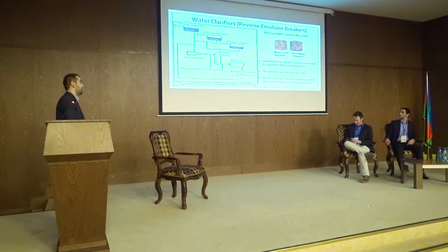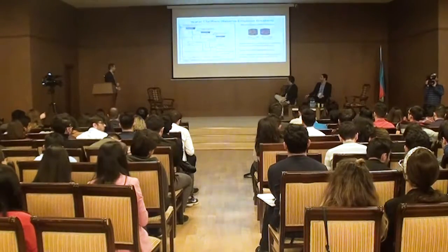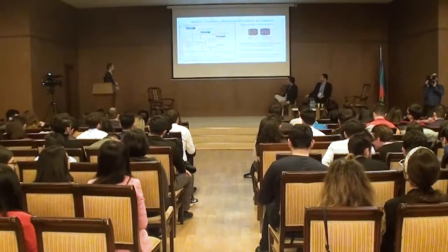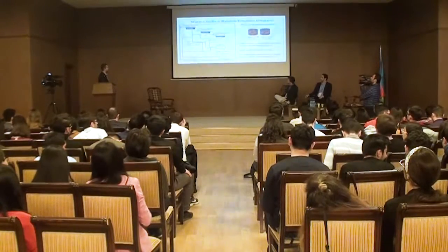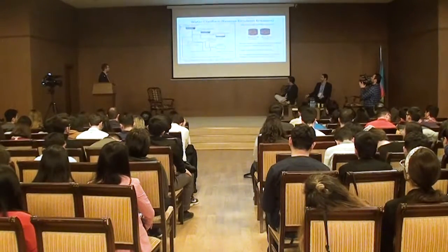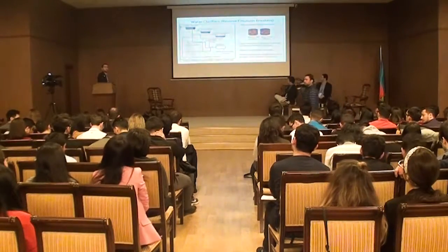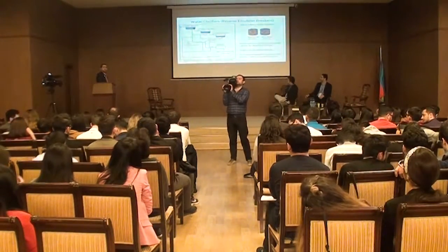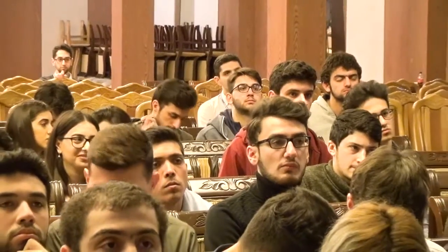So you don't want this because it may plug your pumps, filters, or injection equipment. And I put a typical offshore produced water system in North Sea. While we have water separation in this part of the system, this is a multi-stage separation system where we have water separated here and oil separated here, which is sent for further treatment. But waters from each separator are separated and treated by mechanical treatment units, which are usually hydrocyclone, flotation vessel, or degasser. We need some kind of chemical to help these mechanical units separate oil better.